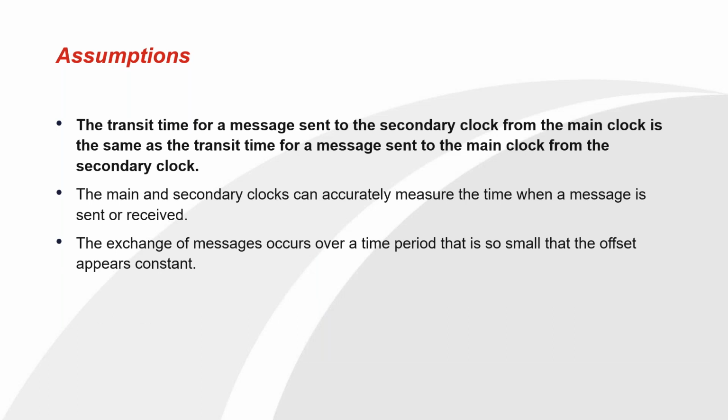It's just worth mentioning at this point that OxTS devices which are implementing PTP can only be set up as PTP masters, so they don't behave as PTP slaves, so they can't be synchronized to another device. They can only be used to synchronize other devices.